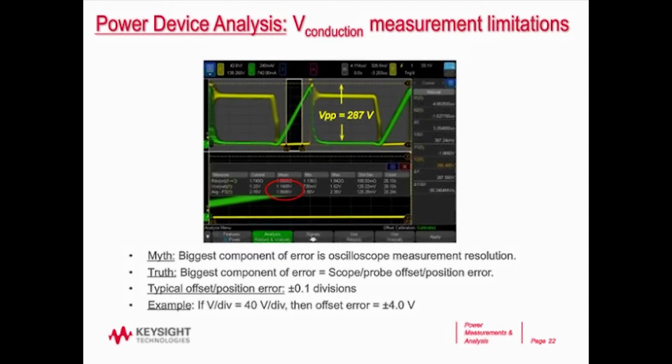Now, if you're really good, typically a differential voltage probe is going to have a thumb wheel or a small screw adjustment that you can visually adjust and null out some of that error, but about the best you could possibly do is maybe half of this, about 0.05 divisions. So for example, let's assume that your error is 0.1 division.